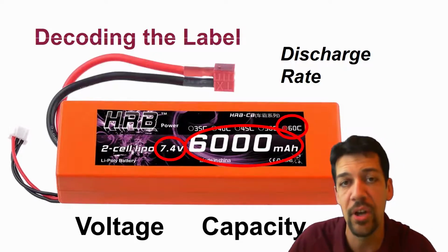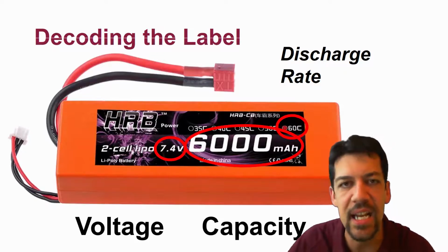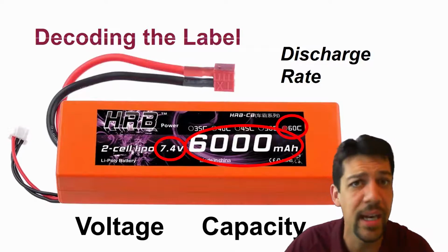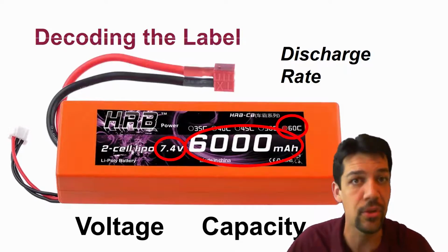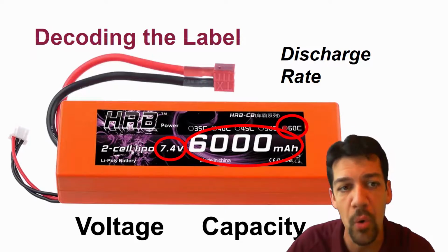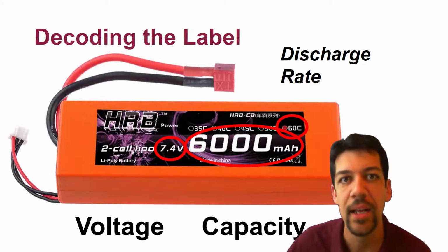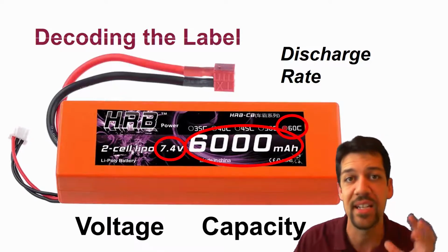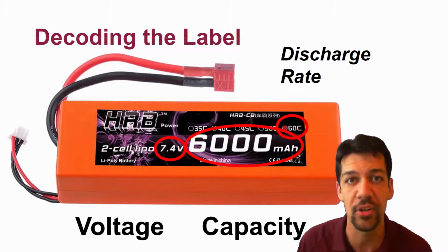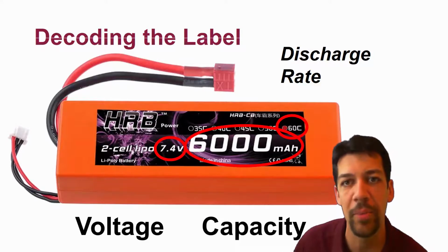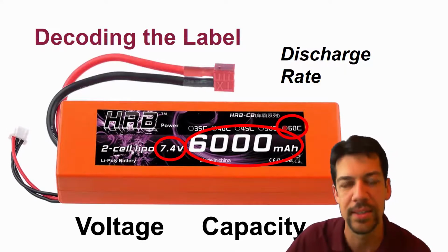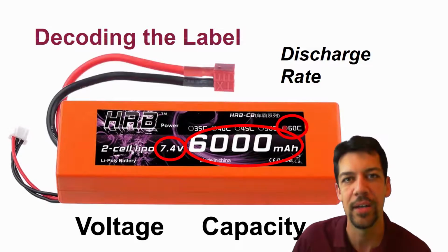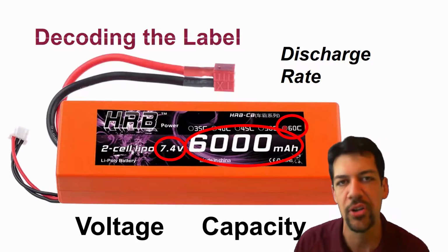Lithium-ion batteries, and actually all rechargeable batteries, have a safe discharge rate of some limitation, right? And basically, if we're drawing more than this discharge rate, the electrochemical reaction happening inside the battery goes too fast, the battery heats up, and it can cause internal damage. It can start to expand and things like that. And that's a big danger for these lithium polymer batteries, as we know from the hoverboard debacles: they can explode if they're not handled properly. So that discharge rate is really important.